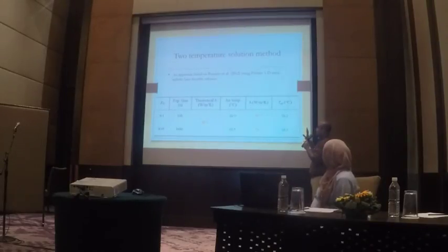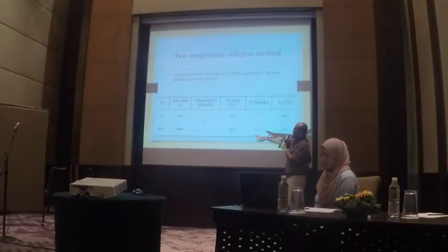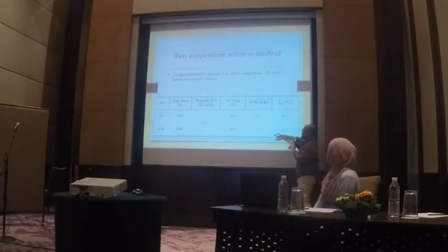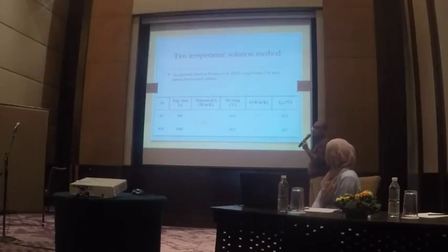So if we use more surface temperature data for the analysis, for Fourier number 0.95, the heat transfer coefficient will be much lower than the theoretical heat transfer coefficient, but the adiabatic wall temperature is the same.